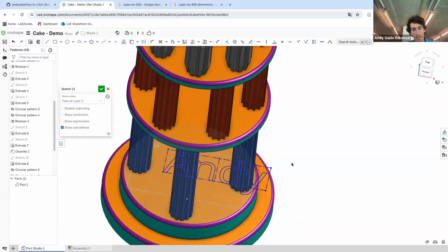Now, here's an area where this software lacks, sadly, which is in SolidWorks, generally the way it works is you can add text, say you just choose the line where you want the text to lie. So you can make it like a curve, you can make it a straight line, it can be anything. And here it's constrained to be a square. At least from my initial investigation, that's what it seems. But that's why you can develop your own scripts, right, to make it different.